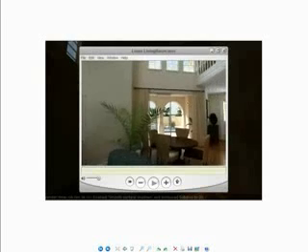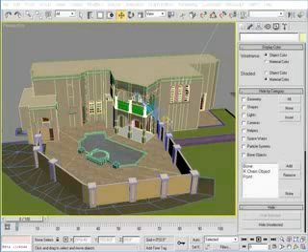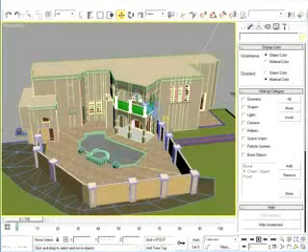Any windows off to the right-hand side, there aren't any, but if there were, those windows and door openings would have intensity values less than the window and door opening fill lights that I have here on the left-hand side of my screen. So from the outside, it looks like in this scene, I should start placing fill lights in these three windows here on the second floor.